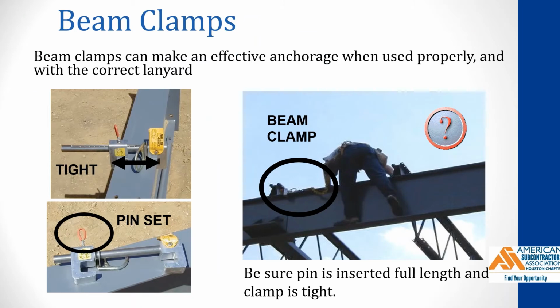Beam clamps can make an effective anchorage when used properly and with the correct lanyard. Be sure the locking pin is inserted full length and the clamp is tight. While you may not typically use beam clamps, they are a good anchorage point.